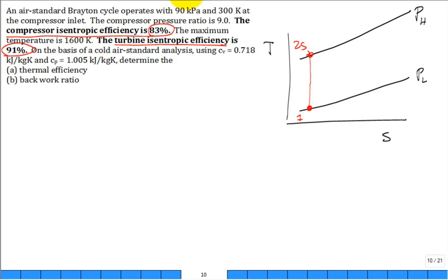So this is a question I ask. Should it go over to the right, or should it go over to the left? I put dashed because of irreversibilities, the lower than 100% isentropic efficiency. To the right. Why is it over to the right and not over to the left? Because when you do a second law analysis, the entropy going out has to be higher. S2 is no longer equal to S1. S2 has to be higher, sweeping away the entropy that was generated because of irreversibilities.